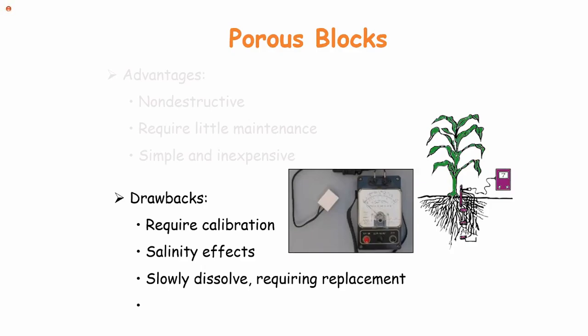The other disadvantage is that since the block is made up of gypsum, it can dissolve in water. If you install it for a long time, it will dissolve and disappear from the soil. In that case, you require replacement of the block. That is one of the disadvantages of this instrument.